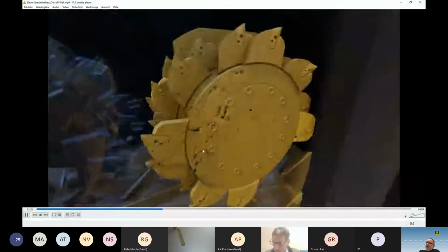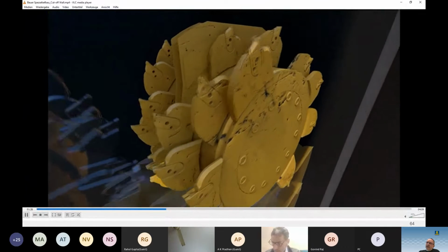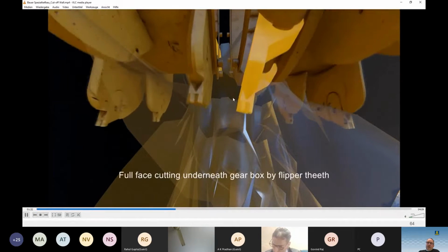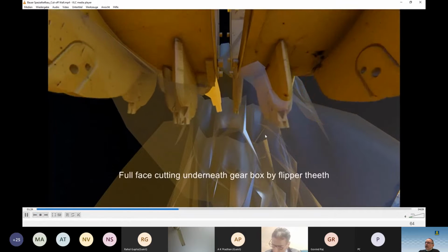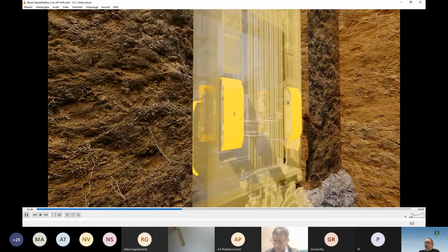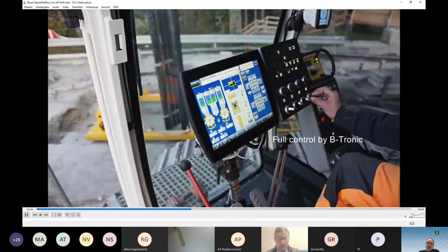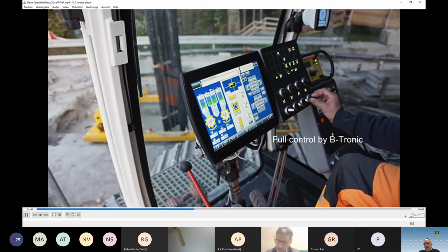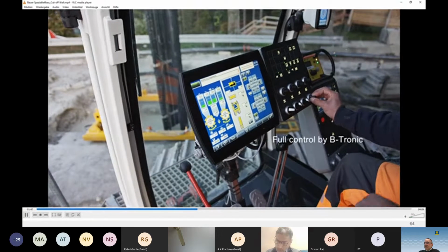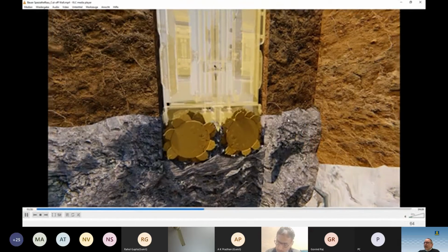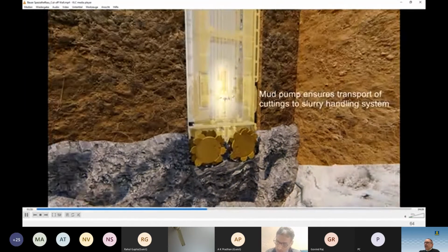The advantage of such a cutter is that you can cut in soil, but depending on the teeth setup, you could also cut into rock. And this is very important for such walls, to have a good embedment in rock. This is often the main reason when you install a new core for such a dam rehabilitation, that you have the core embedded in rock.